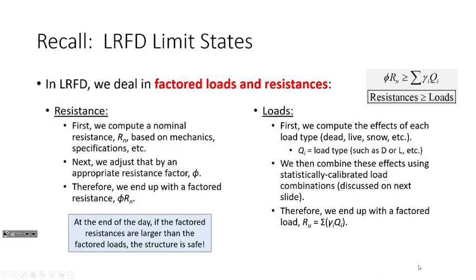So first off, we're all aware that our primary mode of operation is LRFD, load and resistance factor design. So we are factoring both the loads and the resistances independently based on their inherent uncertainty, and to ensure a uniform level of safety. It's why the resistance factor for yielding is higher than the resistance factor for fracture. It's why we use a 0.9 for yielding and a 0.75 for fracture. Remember, yielding sucks, but all it really means is it's getting longer, permanently elongating. But if it fractures, snap it in half, and that's kind of a problem. So that's why that resistance factor is a little lower.